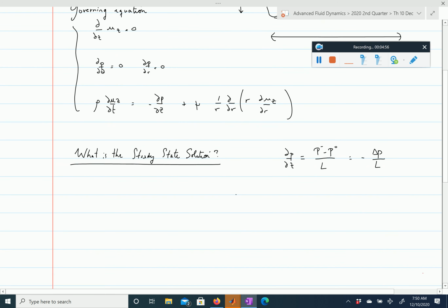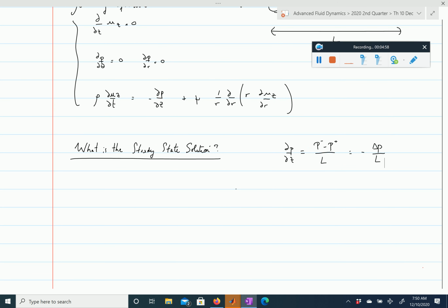So before we just set up the problem, and I'll let you do the derivation, to keep up with our good habit of guessing what the solution is going to look like from scaling analysis, we can do a scaling analysis. What you see from this equation here, once we assume a steady state, is that what is going to drive the flow is the pressure gradient. We have a pressure gradient which is what is setting the flow in motion, and what will prevent the velocity from just increasing constantly if this pressure gradient is constant, is the viscosity.